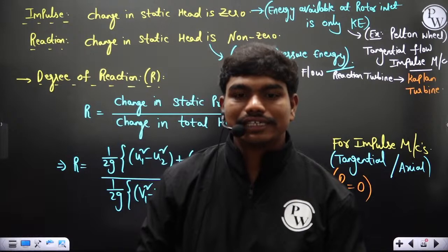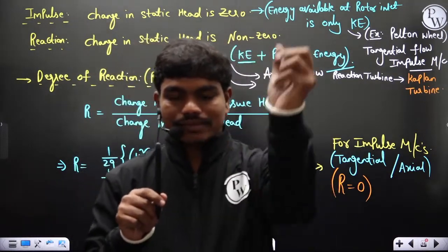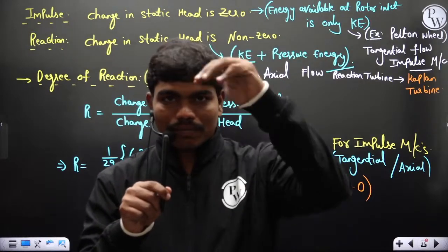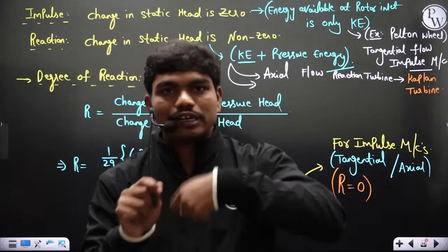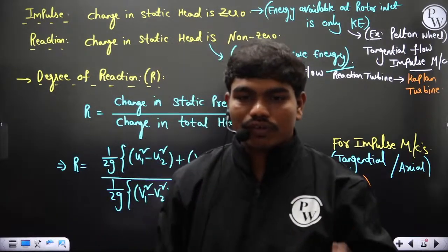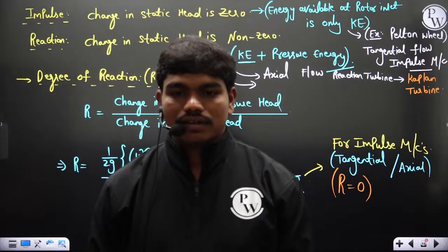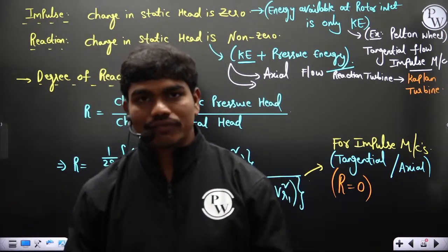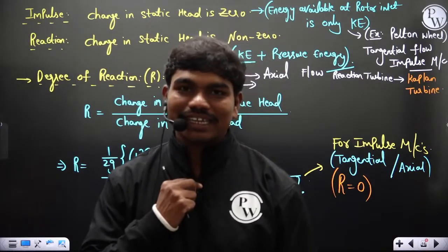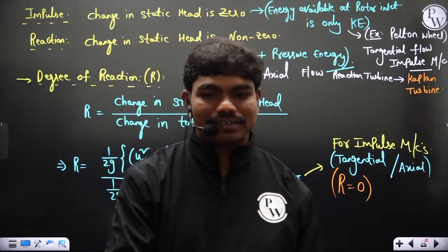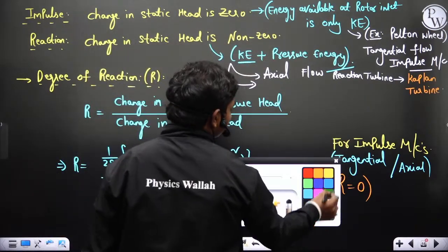All these are actually Kaplan turbines. When you are running, it's basically an axial turbine. Whenever flow comes and the blades are designed at a certain angle, when the fluid passes through them, it rotates, so the fluid imparts some power onto this. You might have seen them at different locations, but you didn't know at that point of time that it was a Kaplan turbine. Clear? So anyway, it's an axial flow reaction turbine, the Kaplan turbine.